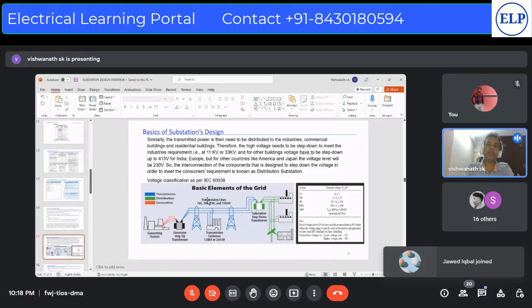One should know these things, very, very important, because you cannot do 66 kV or 132 kV as an indoor substation. You have to go for an outdoor substation, an outdoor switchyard. The kind of design remains totally different, but you will see the same kind of equipment in different switchyards, with different types of installations and a different approach when you do the switchyard designing.